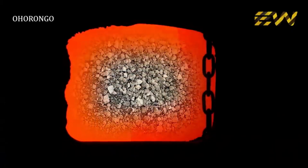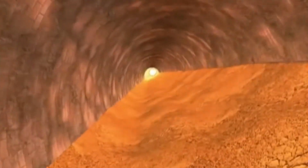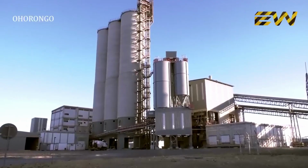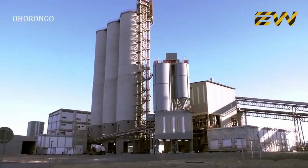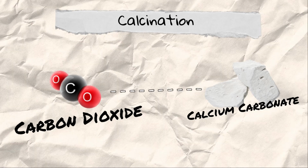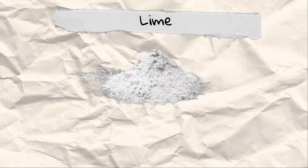As it passes through this tall vertical tower, hot exhaust gases from the kiln below heat the powder to around 1,000 degrees Fahrenheit. This preheating process initiates the beginning stages of calcination. Calcination refers to the dissociation of carbon dioxide from the calcium carbonate in the raw meal, yielding calcium oxide, also known as lime. The partially calcined meal then enters the kiln from the top of the preheater tower.